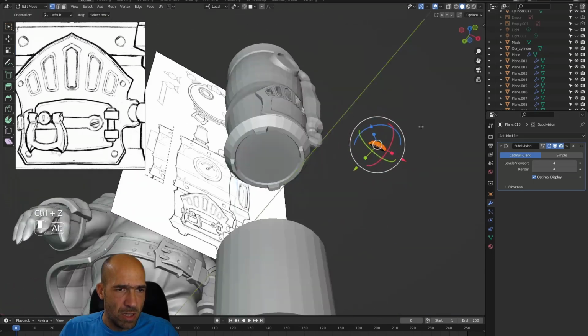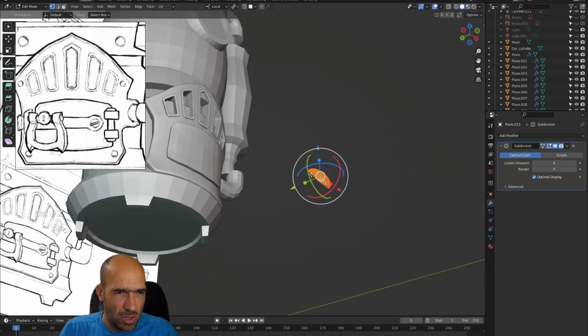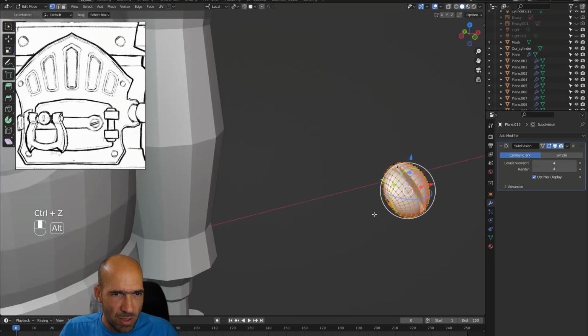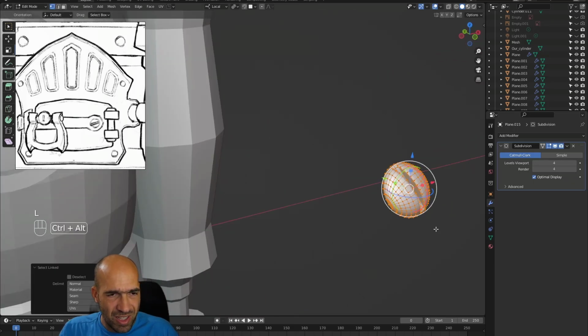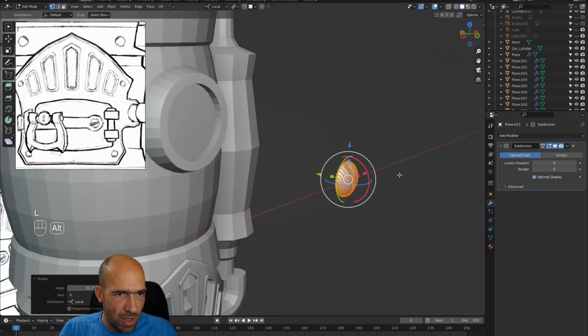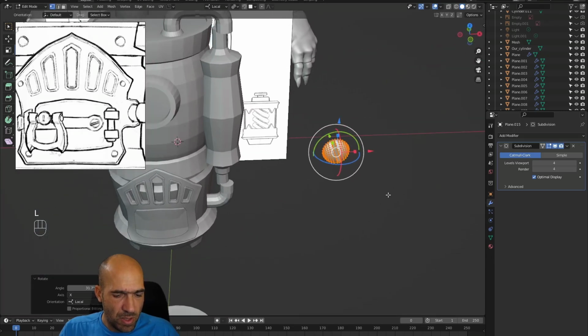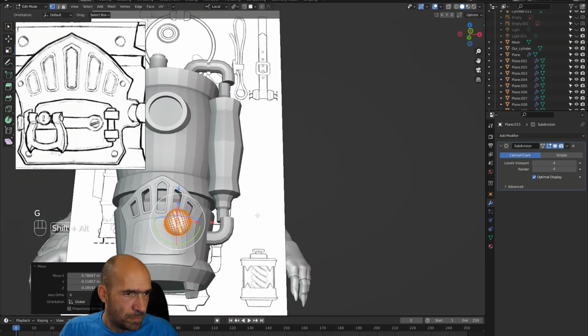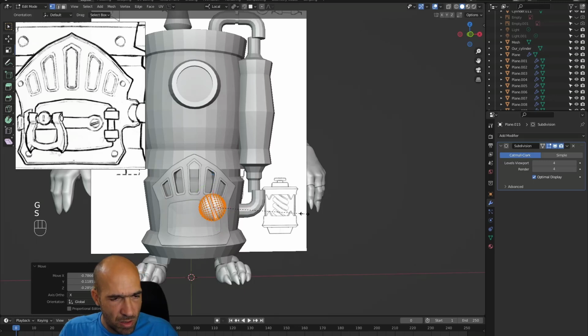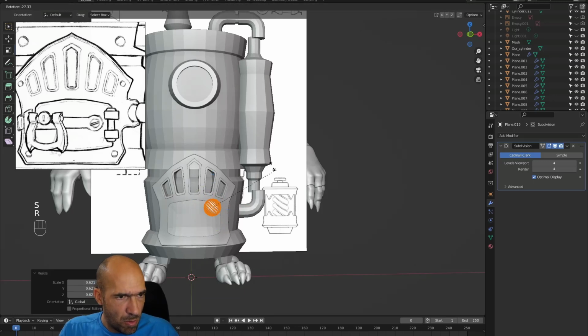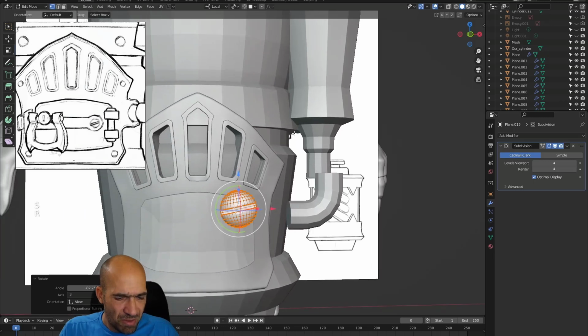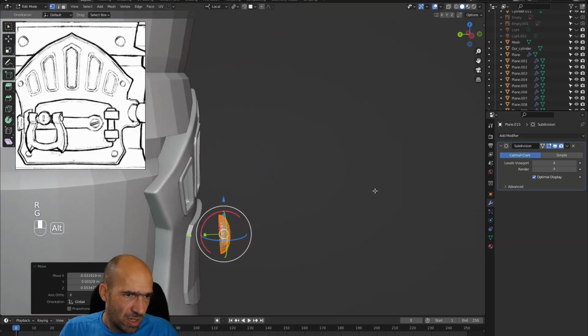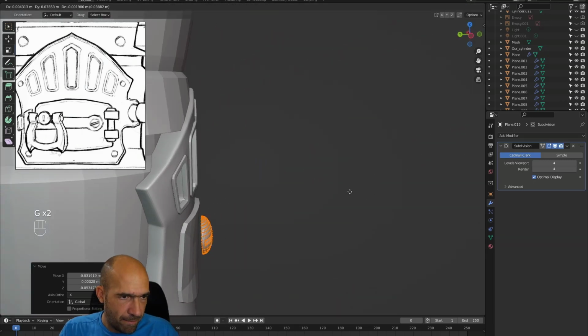But first I need to be able to select all of it. So press L or just A, who knows, and then rotate it and put it into position and make it smaller, of course. S. Maybe I will rotate it a little bit, and this, of course, I will just try to adjust it by hand.